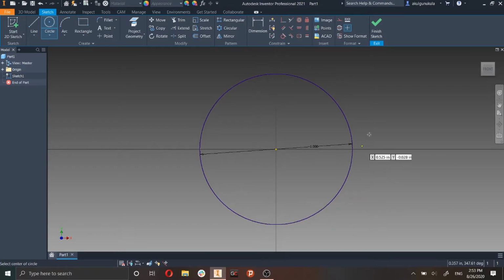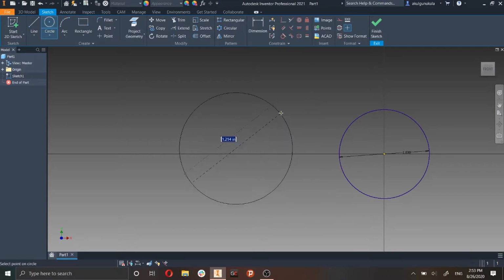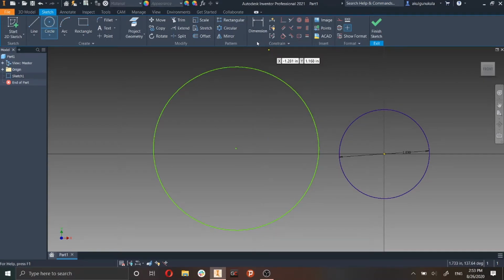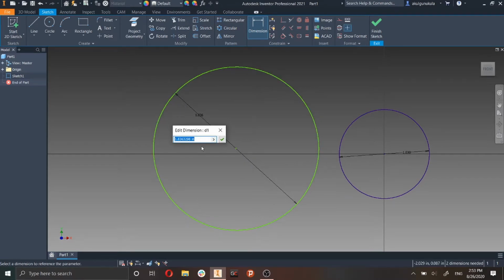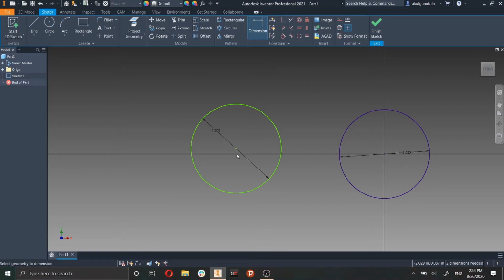That is one way that you can dimension a circle. I'll show another way now. Same way as a line. We first freehand the circle, and then we'll use the dimension tool to dimension the circle. So let's dimension it. Select the dimension tool and select the circumference. So now let's put the measurement taker, let's say right here, and let's type in what we want it to be, 1 inch. There we go. So now let's press the escape key to unselect the dimension tool, and now we have a 1 inch circle that can still be moved.